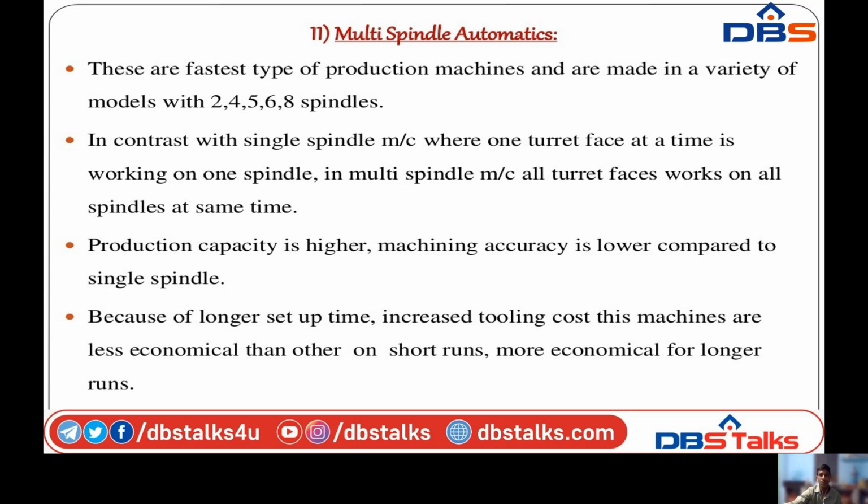What is the difference between single spindle and multi-spindle? In single spindle we are using a single spindle for machining. In multi-spindle we are using 2, 4, 5, 6, 8 spindles at a time. Why are we preferring multiple spindles? Because higher production rates are there. In contrast with single spindle machines where one turret phase at a time is working on one spindle, in multi-spindle, all turret phases are working on spindles at a time.